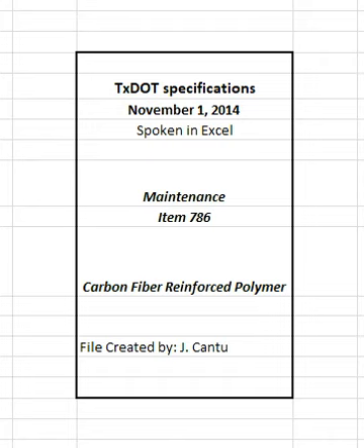3.1 Qualifications. Provide documentation from the CFRP manufacturer showing project personnel have completed training on the CFRP system selected. Ensure trained personnel remain at the work site at all times to install and direct the CFRP field installation work. Provide documentation for concrete member strengthening work to demonstrate previous CFRP field installation, including successful completion of at least 3 CFRP field installation projects similar in scope and magnitude to the work.